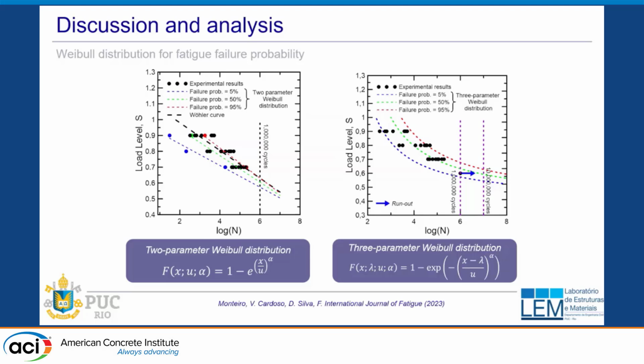So two-parameter Weibull would give us a linear curve, and a three-parameter Weibull gives you a slightly better curve fit, but now you have a nonlinear type of curve. Going up to 1 million cycles, the tests were run at different levels, 90%, 80%, and 70% of the upper limit value, to generate the SN curve. So these are the basic SN curves of the samples.